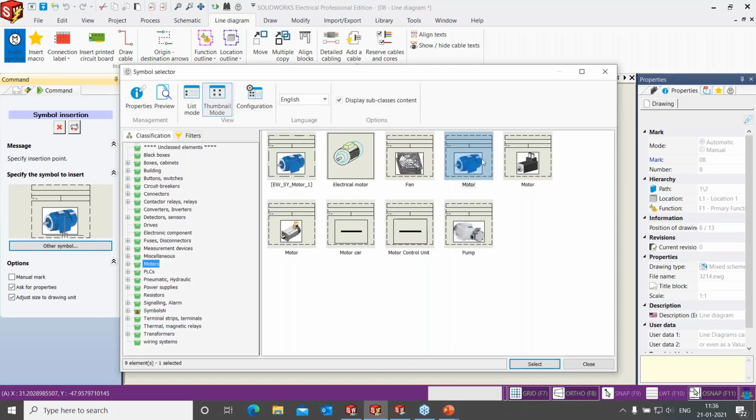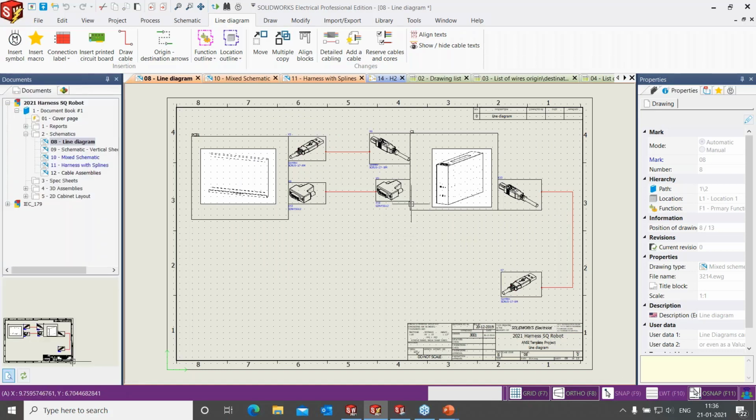As you can see here, in single line designs, we use pictorial representation. Why pictorial representation? Because when we release the drawings to the layman, it's not always the electrical designer who will be at the installation process. There can be a lineman who will be taking care of the installation at times. So it shouldn't be difficult for him to understand. With the help of this pictorial representation, he can just view the pictures and start rigging up the circuit. So this is one advantage.